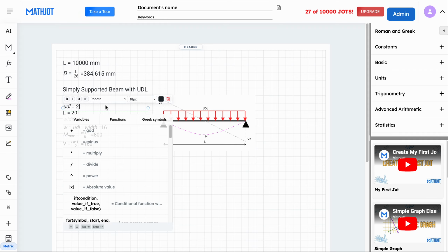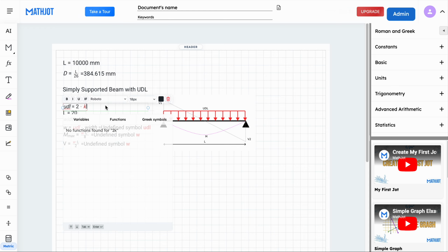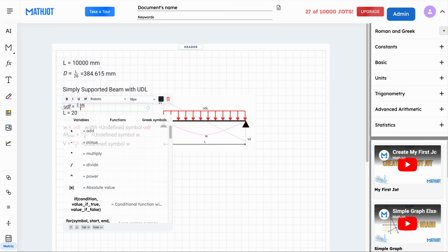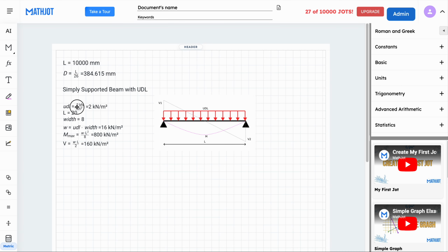Most of these calculations come with predefined variables in there, but they're obviously not the ones you will want to use. In this example we're using units, so I'm just going to go through and add units in. We often don't include units in the actual calculations because often people don't want to use them directly, and you can just add them in if you want to. When you do units, make sure that you are consistently using units, or consistently don't use units. If you mix some units, some without, you'll get some very interesting results, and it probably won't be what you want.